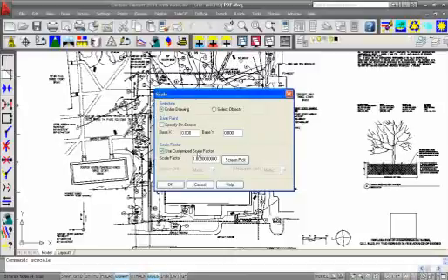Use customize scale factor. On this job, that's what we're going to do. But if I uncheck this, you can see some other scaling options that are going to be useful with other drawings. If you're bringing in a CAD file and say it was in inches, it was an architectural, and everything you do, you want to be working in US feet, you can see the scale factor is grayed out, but it's 0.083333, repeating.